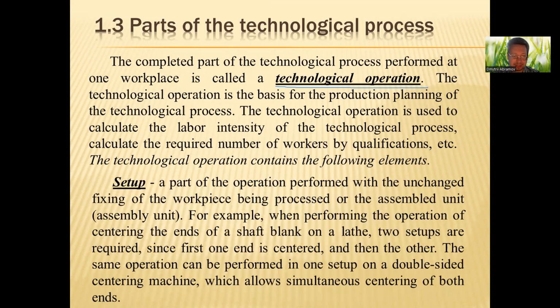Setup. Setup is a part of the operation performed with the unchanged fixing of the workpiece being processed or the assembled unit. For example, when performing the operation of centering the ends of a shaft blank on the lathe, two setups are required, since first one end is centered and then the other.